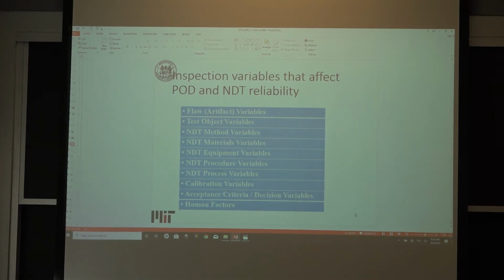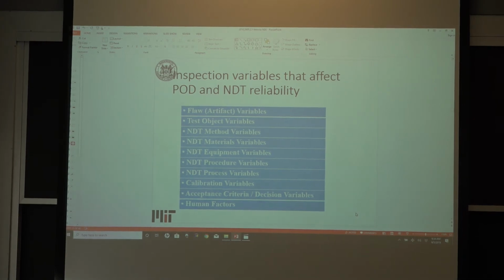The object that you're testing, the equipment. The equipment can actually be a source of electronic noise. And if you are looking at something where you're trying to determine microstructure, like 300 micrometer size flaws, something that is not macro scale, the equipment that you're using, the electronic noise, can be enough to result in false positive indications.